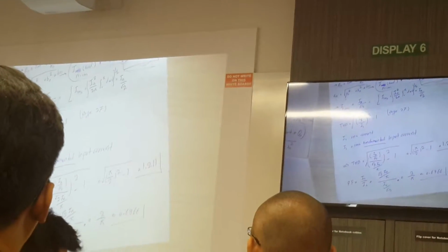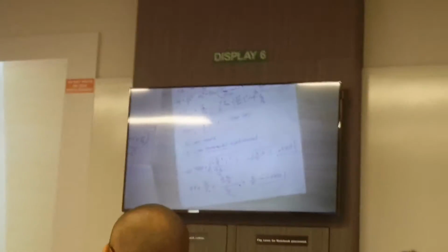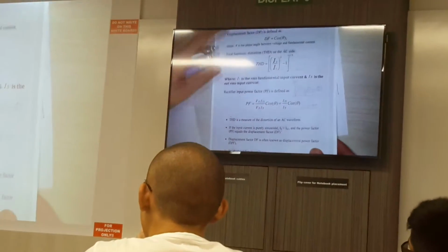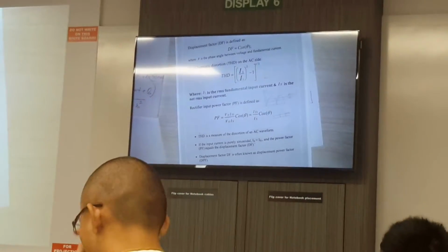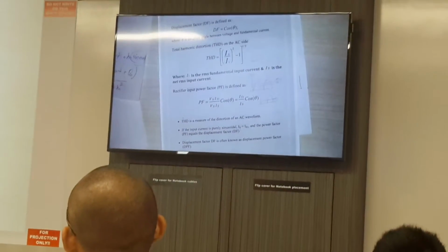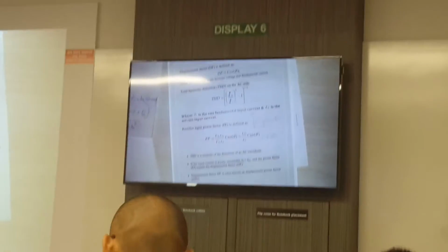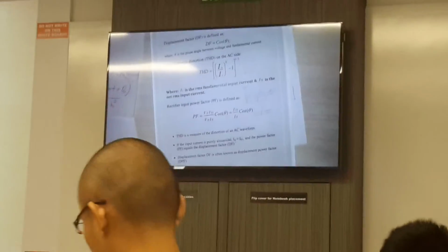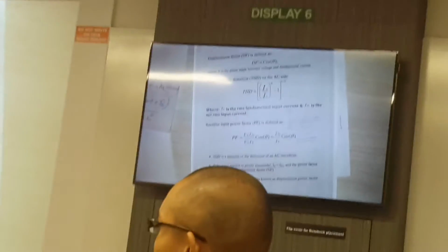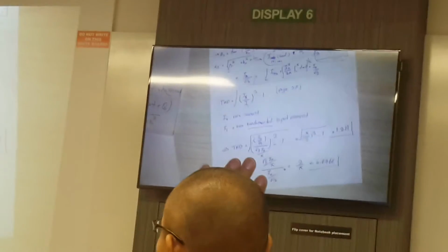For the THD, or total harmonic distortion, tomorrow you have the lecture and the professor will teach you this equation for the THD, which is IS, the whole RMS of the signal, over I1. I1 is the RMS of the fundamental frequency or fundamental signal. But again, IS is the RMS of the whole signal, because I have calculated the IRMS according to the signal itself.